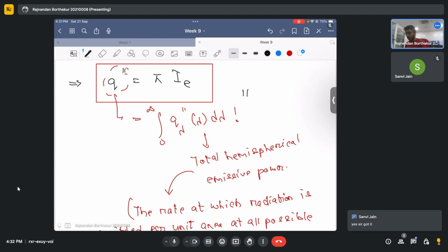Okay, so if it is clear, let's first think about what we learned. We started off with the radiation fluxes. We saw what kind of fluxes we need to deal with when we study radiation. Once we knew these fluxes, we saw that they are not mere fluxes as we deal with in conduction and convection, because the properties in radiation show dependence on the direction as well as the wavelength. If we have a property that is dependent on wavelength, it's called a spectral property. For instance, the emissivities, the emissive power, the intensity of radiation, all these are spectral quantities because they show dependence on the wavelength.